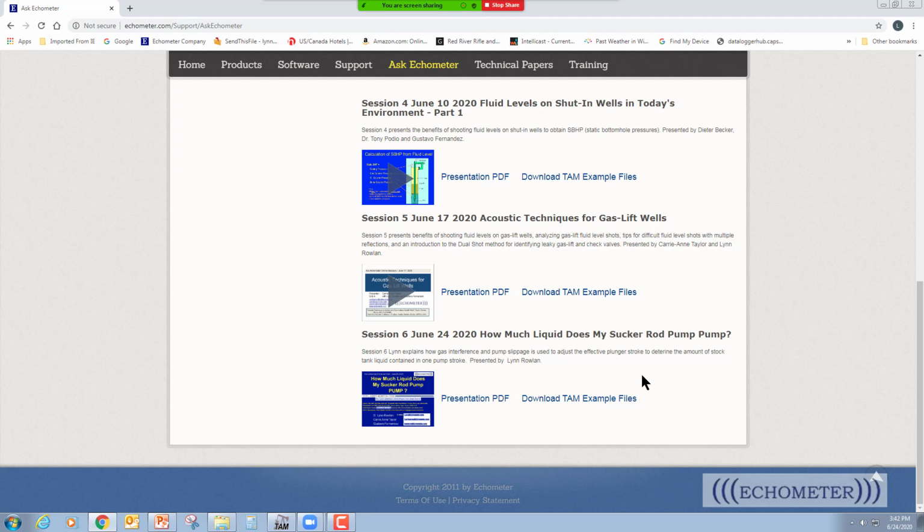Now, another thing you can do is there's a paper on troubleshooting rod pump wells by shooting down the tubing. You can shoot down the tubing and see if you have a liquid level not at the surface, and that would maybe indicate you're pumping the liquid out of hole. So there's some things you can do. Download that paper off our webpage. It's called Troubleshooting Rod Pump Wells with Acoustic Instrument, and it's a paper that John Sparks and I wrote, along with Joe Norman, pressure testing the tubing with a wireless pressure transducer. Those both are good papers for reference on that question. But sure, that could be a problem.